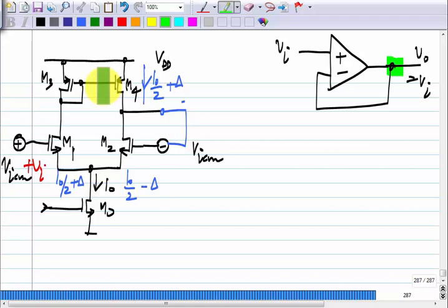Okay, so that is what happens in an op amp, right? This can be described in many ways, but the virtual short finally happens because of negative feedback, these two currents will be forced to be the same. So, that means that this gate voltage and that gate voltage will have to be the same. Okay. So, that is how the virtual short occurs in an op amp. Is this fine? Now, in presence of GDS and so on, there will be some small errors that you can analyze, right. So, you should be able to figure out the same things either from large or small signal reasonings, but this is a unity gain